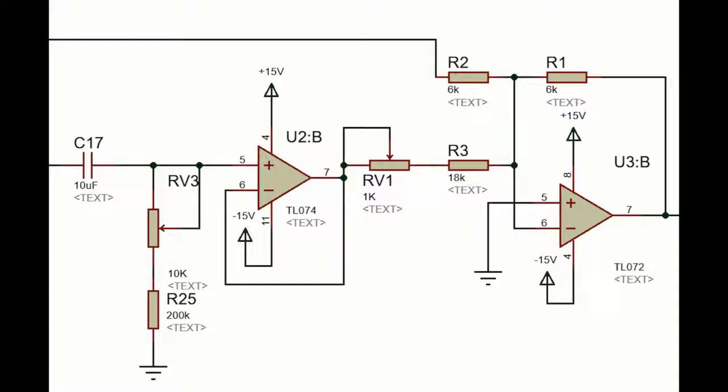During rapid changes of angle, I need to use the gyroscope signal, hence it has a high pass filter. Matching the time constants of these two filters ensures the transition occurs smoothly and dynamically between these two signals. I merge the two signals instead of switching between them. Okay, so let's explain what I mean by merging the signals.